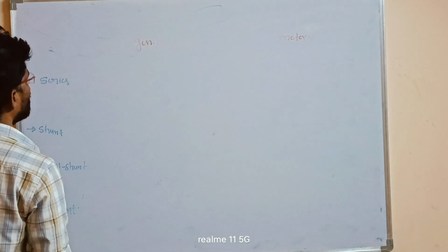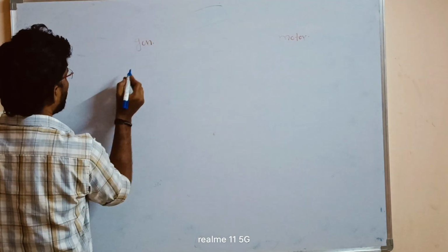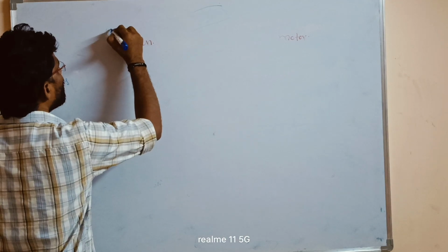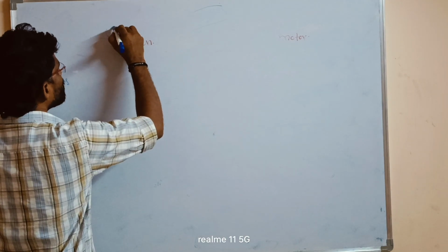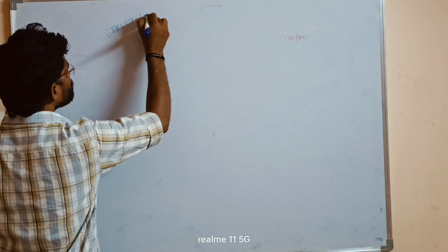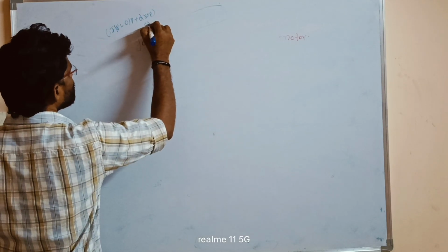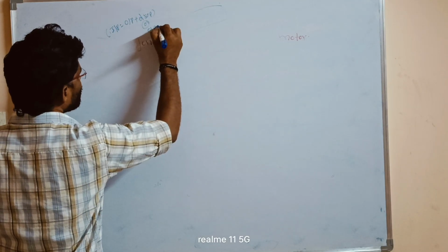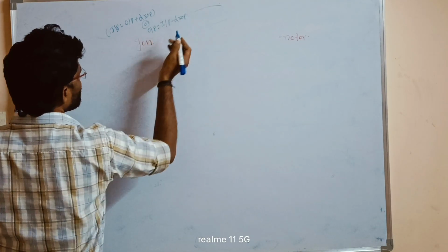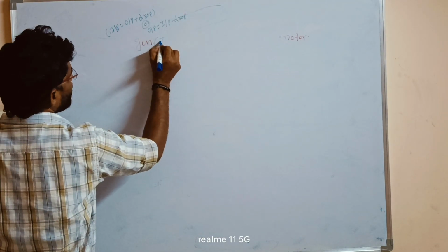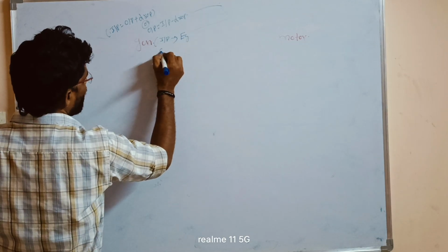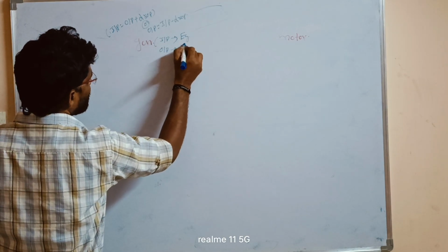Short shunt and long shunt. In the case of a series generator, we can always follow the formula: input is equal to output plus drop, or output is equal to input minus drop. Here, the generator input is EG, and the output is the terminal voltage.